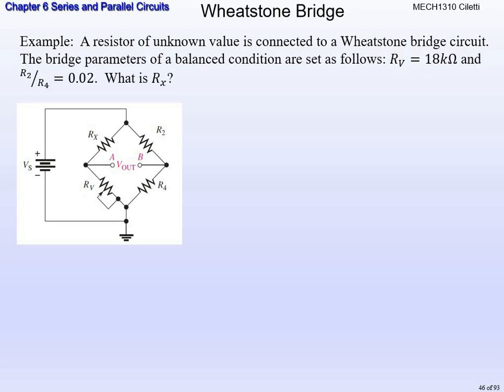So after you draw down the Wheatstone bridge, what we need to do is Rx divided by RV is equal to R2 divided by R4. So that's the relationship. Alright, we talked about that early on. Instead we used what though? R1 and R3 and R2 and R4. So that's why I said don't memorize which R it is. You got to look at the actual schematic and use the given R's.